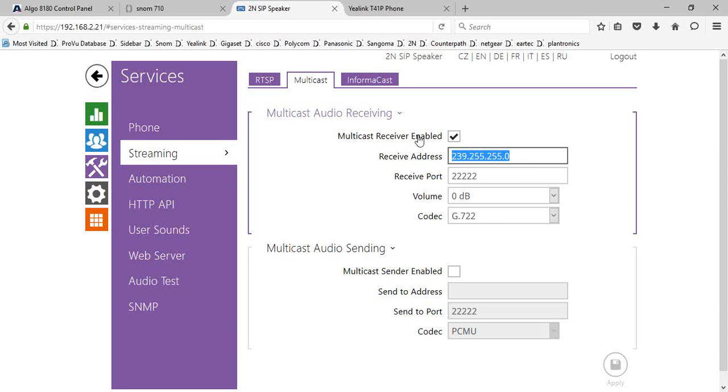Okay. And just to add before we move forward, there's a multicast audio sending option, as you can see on the screen as well. So the same device effectively can act as a master and a receiver at the same time. And TrueN have used this in certain scenarios where all these devices we're talking about have a built-in dry contact relay. Most of the old alarm systems or paging systems worked by sending a signal to the main amplifier on a dry contact, and that dry contact effectively initiated a decoding message to be played across the board.